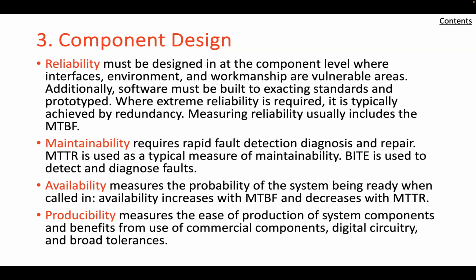There's also something called built-in test equipment, or BITE. A direct means for reducing the MTTR of a system is to incorporate auxiliary sensors that detect the occurrence of a fault that would render the system inoperable or ineffective when called upon, then signal an operator that repairs are required and indicate the location of the fault. Such built-in equipment effectively eliminates the time to detect the fault and focuses diagnosis on a specific function.